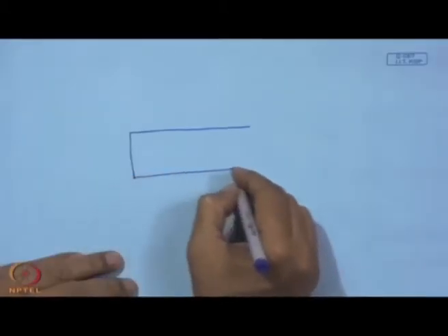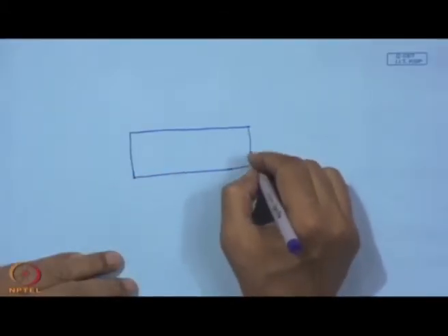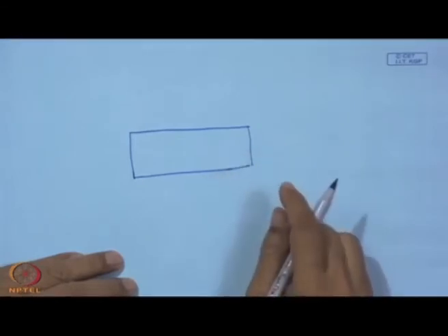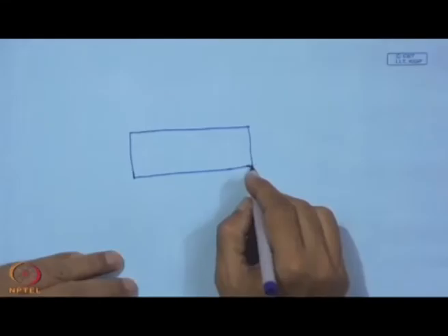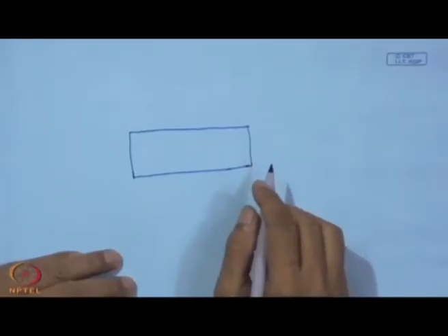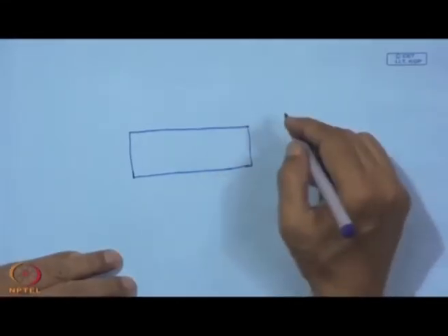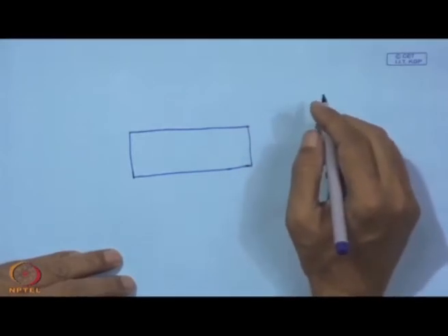So, what is done here? In fact, this is just a flat surface, it can be small, rather we should use it for micro tools, for all sorts of micro machining, micro working, this micro diamond abrasive tool. Let us consider it schematically: this is the receptor surface where we would like to have the deposition of diamond.